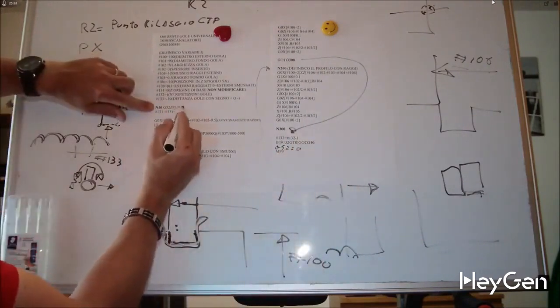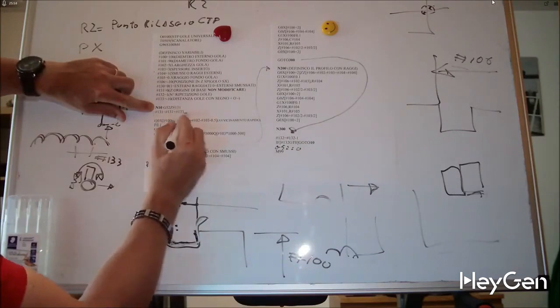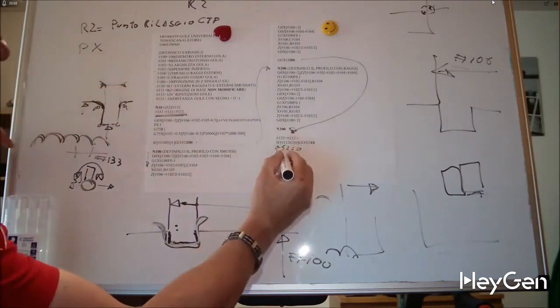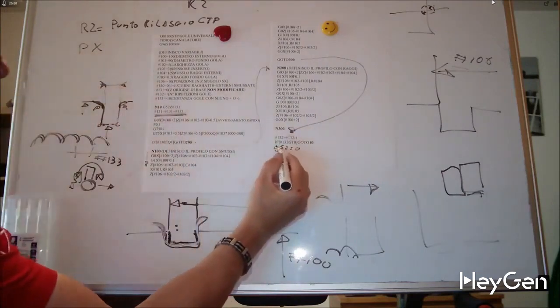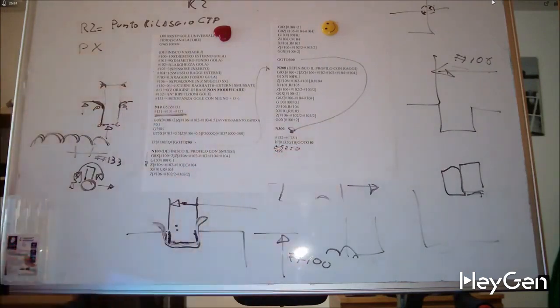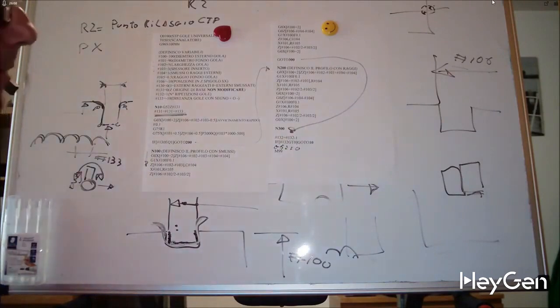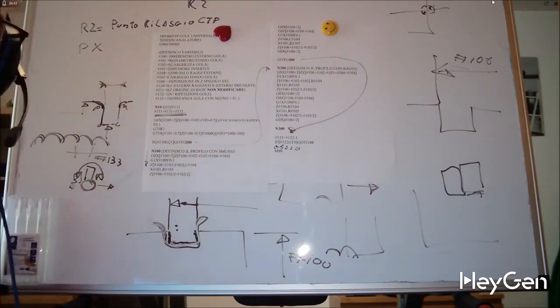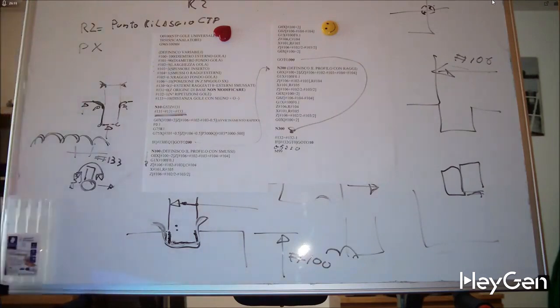That is my origin, calculated according to this little equation. If it's equal to 0, I go to M99 just to be thorough. I set G52 to 0 and there we have finished our program, allowing it to make choices.